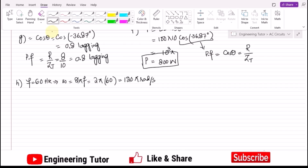In order to find the total voltage here, the value of the total voltage was 100 at 0 degrees, where this voltage is the RMS value, while this is the phase angle. So in order to write them in the form of the sinusoidal wave, I should have the peak values.